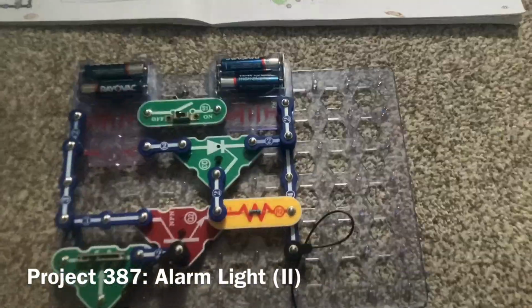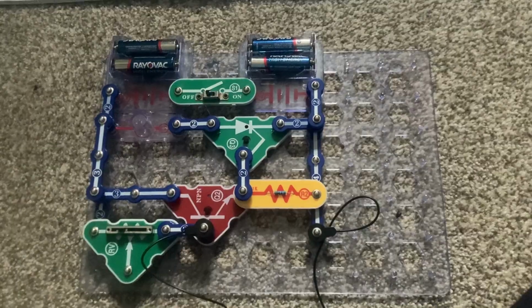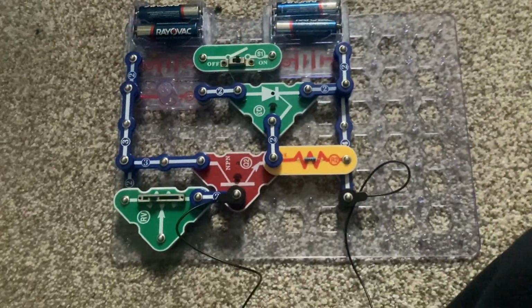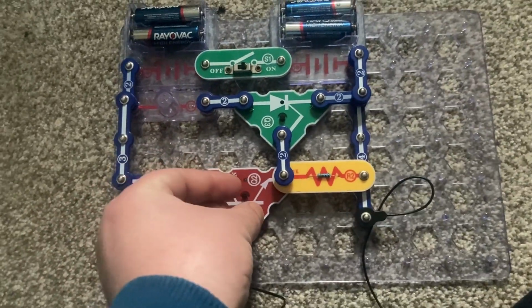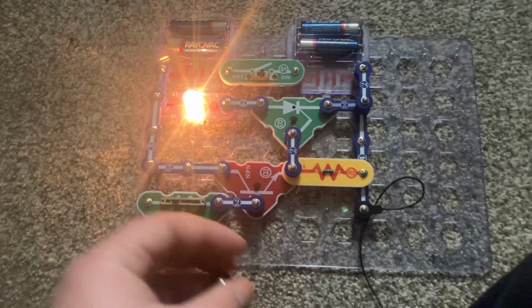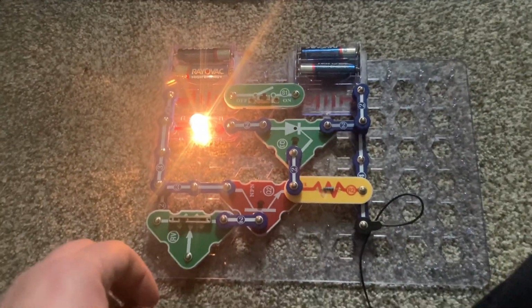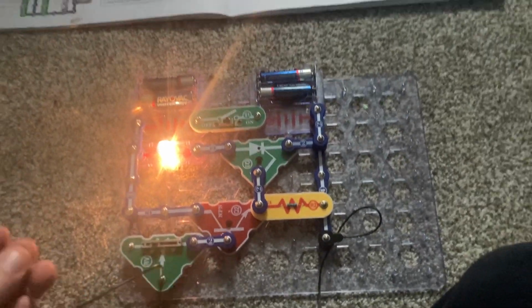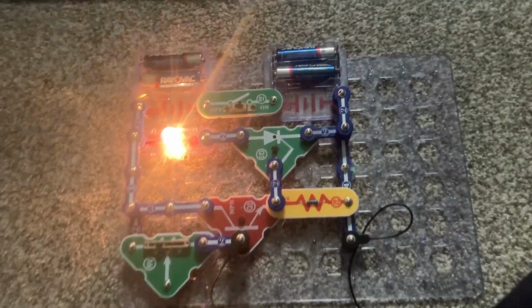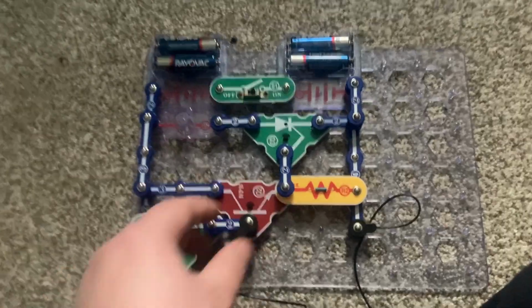This is another alarm light, except this one uses the Q2 transistor to work. However, the principle is the same. When I turn on the slide switch, nothing happens. Then when I remove the jumper wire, the lamp will come on. You could pretend that you have a longer wire running across a doorway, and then if an intruder removes or cuts the wire, the lamp will come on. And it will stay on even after you reconnect the jumper wire. So to reset the circuit, you have to turn the slide switch off and back on again. And you can do it again.